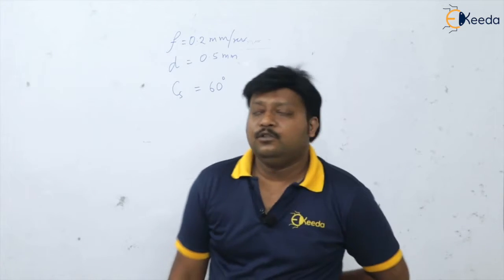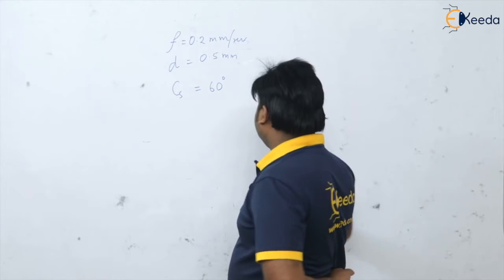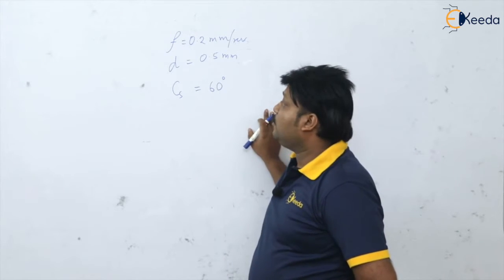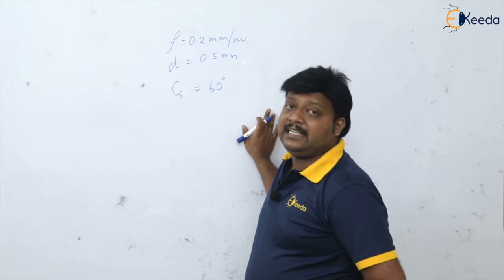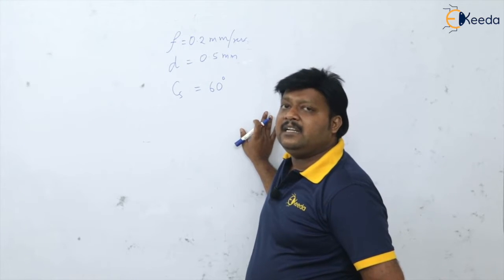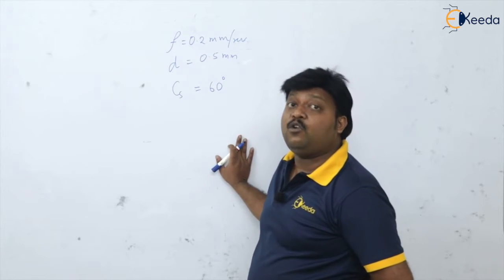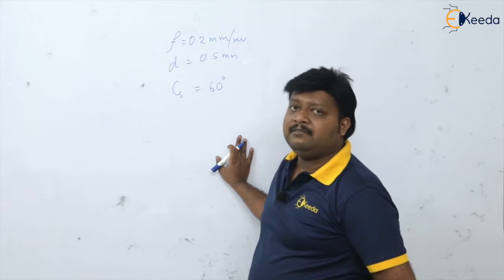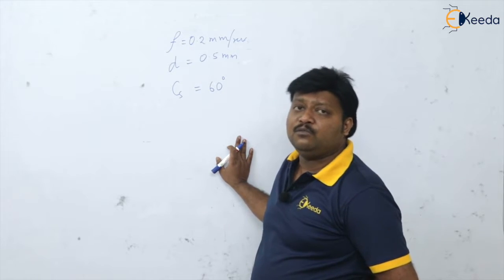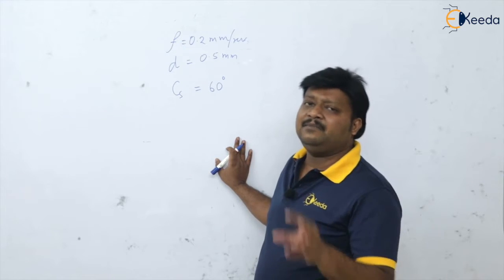Okay. So please remember that whenever in the question they are talking about the side cutting edge angle or the principal cutting edge angle, then there are a lot of chances that the given operation is the oblique cutting operation. Whenever they want to ask a question on orthogonal, you will find that word orthogonal every time in the question.